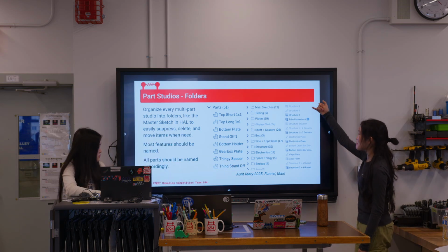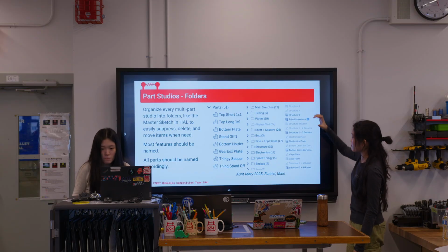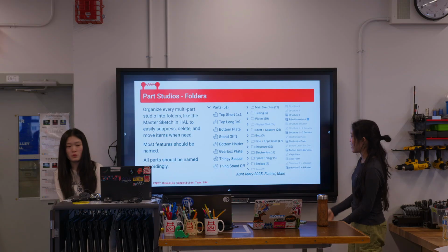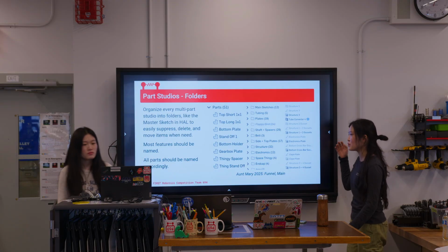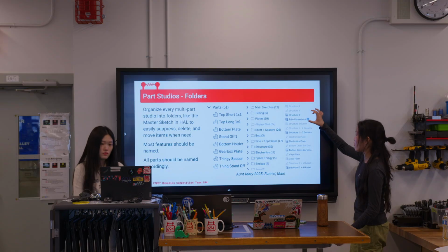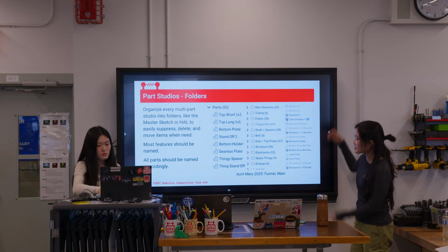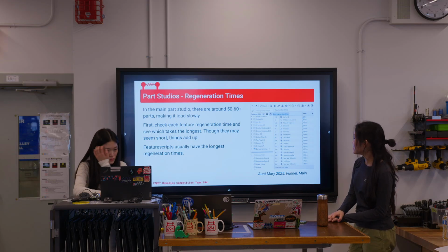I usually name the plane, extrude, and sketch by whatever they're related to, so I don't have random plane number 3 and extrude number 1. It's really easy to tell when you derive into other documents if you have all the names, so you can import them all together. So it's nice if you can name all your features, maybe not all, but most of them.